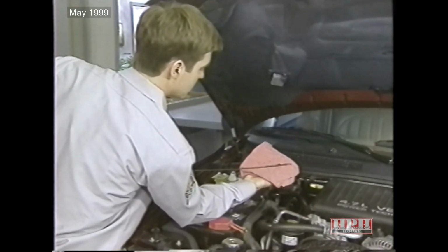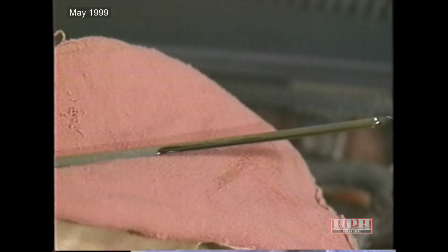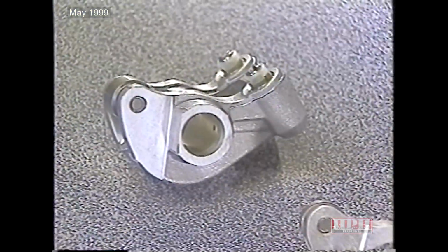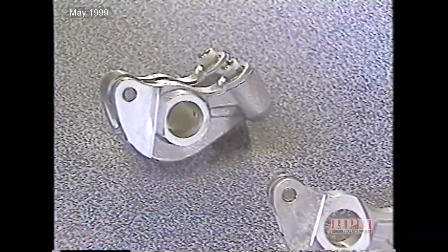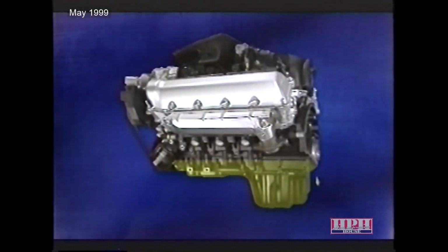As with low levels, high levels of engine oil or transmission fluid can cause their share of trouble. An engine with too much oil can exhibit the same valve train noise that low oil levels can produce. When the engine has too much oil, aerated oil can enter the lifters and cause them to become spongy or sloppy. Too much oil can also cause oil to leak from otherwise good seals or gaskets.